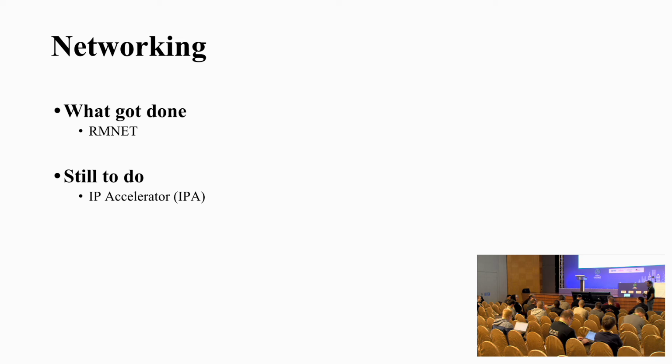But then you're absolutely right that this is essentially coming to the same code that we already have there. Yeah, and in the remoteproc case, we also have the problem that traditionally we used the DMA alloc. However, it used the bitmap allocator, where you don't specify the size in bytes, you specify an order. And conveniently, one of our firmwares is 34 megabytes in size, so we would waste quite a bit of RAM by doing that.